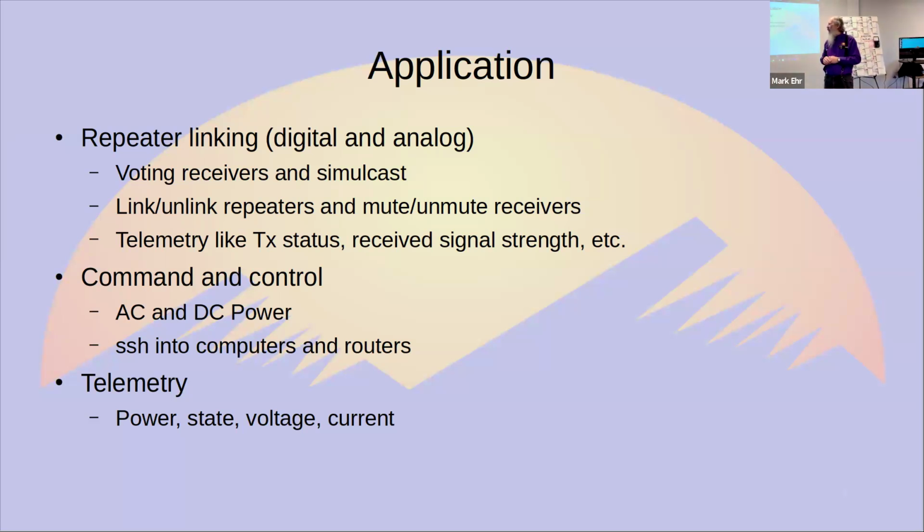The other issue with this, of course, is that when you're going these really long distances, the time of flight gets up in the millisecond range, right? So the speed of light is roughly 6 miles per microsecond. And so if you've got a 60-mile shot, that's 10 microseconds just to get over there and 10 microseconds just to get back, plus whatever delay there is in the radio.